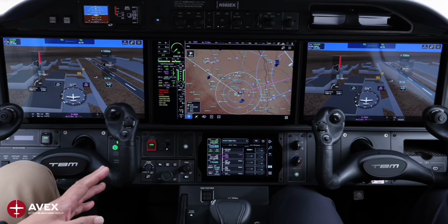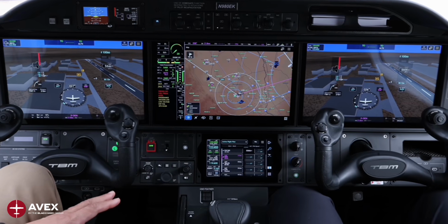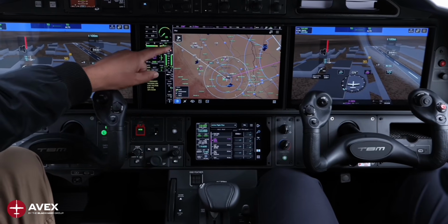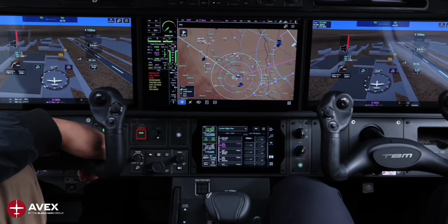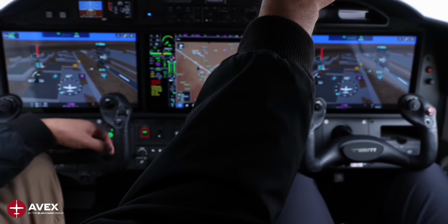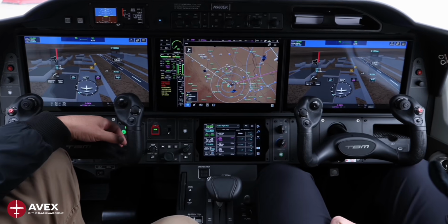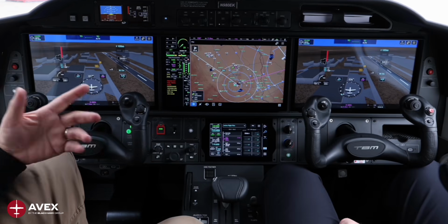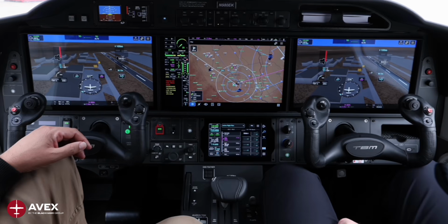So the big deal now is that we are anti-ice free. There's no need to put Prist or anti-ice fuel additive on the aircraft. So now we do have a fuel pressure indicator up here. It's usually in the 40 psi range, and the boost pump is always on. There's no more auto. It's always on, from engine start to engine shutdown. That is really cool. We don't have to worry about adding it, especially if we're at a faraway airport where we need to take cans. We don't have to do that anymore. Yeah, that's really nice. That is probably the best thing about the 980.